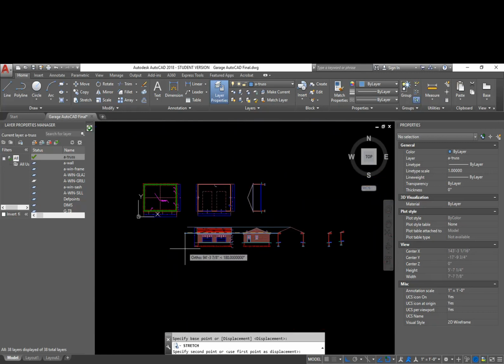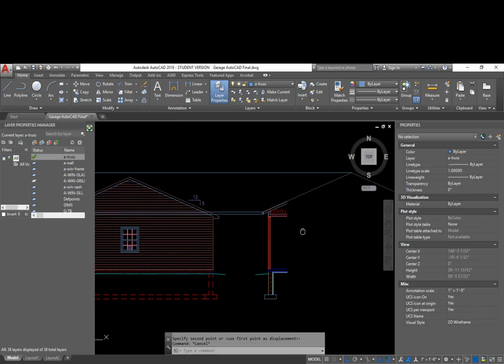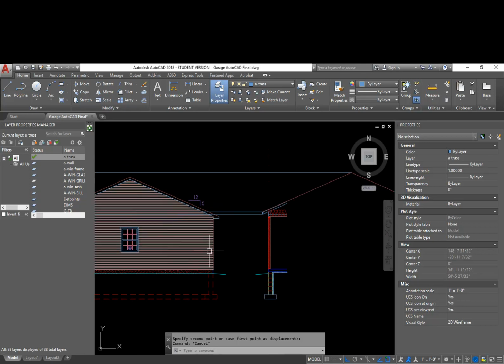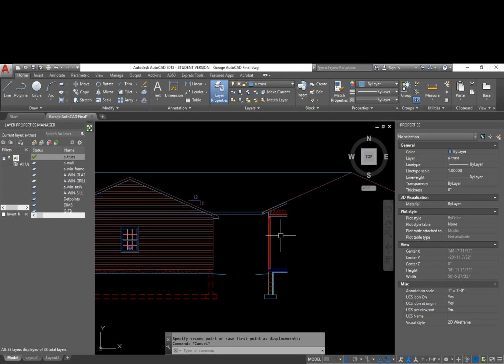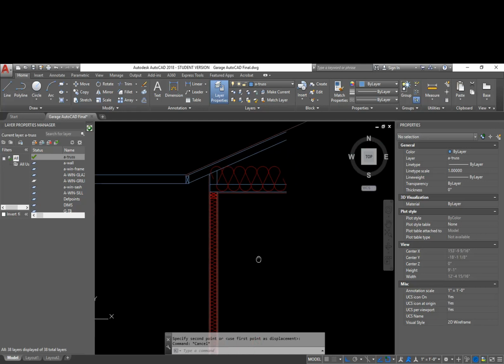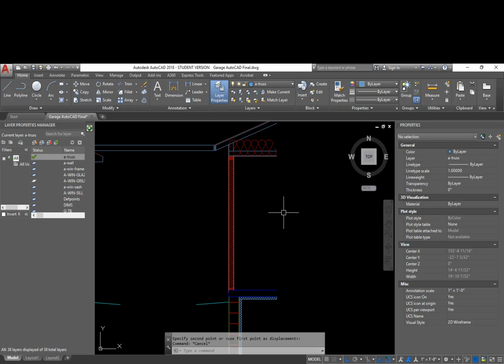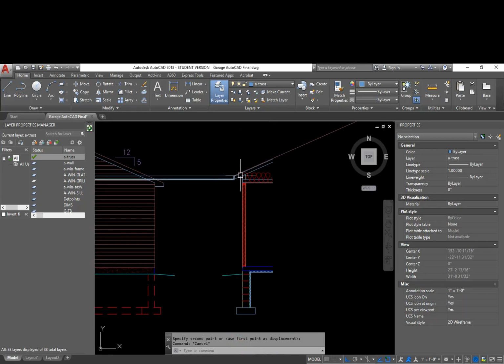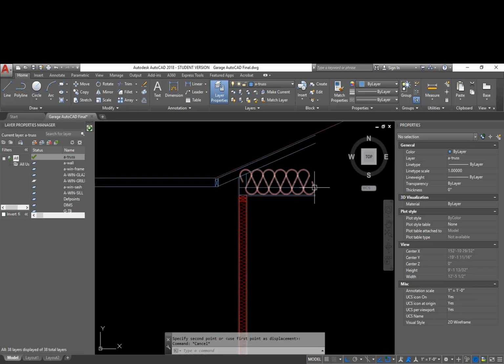So a lot of times, if I'm doing a design, most of the time what I'll do is I'll have all the details of the wall section worked out before I start doing elevations. So the debate is whether to do this or not. If I was doing a house design, I would definitely add this as a feature because I'm very concerned about losing heat. The idea with this garage is it's only going to be heated to a very low temperature, around 50 degrees, basically keeping it from freezing, and we're not really too worried about it. It's probably going to be heated only on occasion, so we're just going to forget about doing this raised heel. And I wanted you to understand that if you're doing a residence, this is a really good way of doing the design.